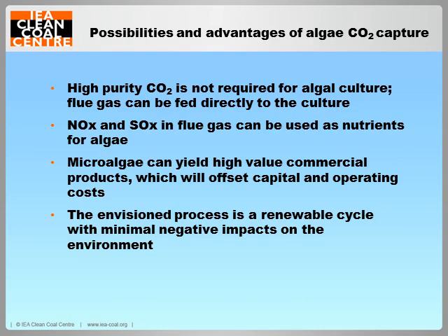The possibilities and advantages of capturing CO2 from the flue gas by microalgae are as follows. First, algae is not very fussy about the purity of CO2. Flue gas can be fed directly to the algae culture. Secondly, NOx, SOx, and some heavy metals in flue gas can be used as nutrients for algae to grow.